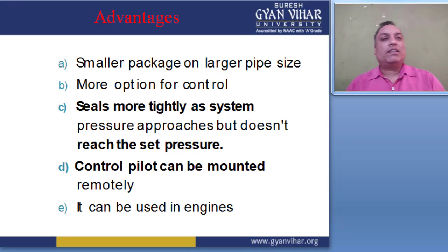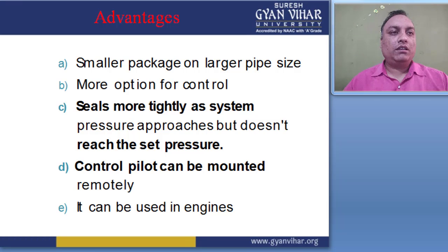For the advantages, it creates a smaller package on a larger pipe size. It gives more options, and the seals seal more tightly as system pressure approaches, but does not reach, the set pressure. The control pilot can be mounted remotely, and it can be used in engines also.